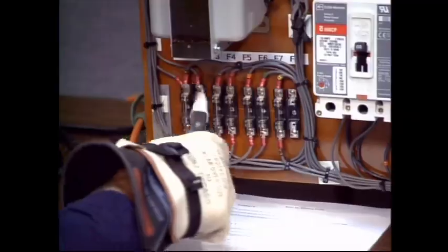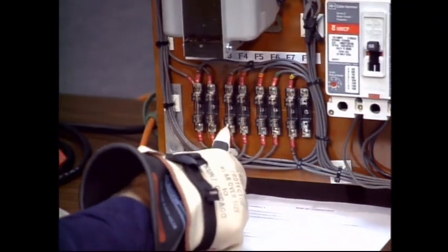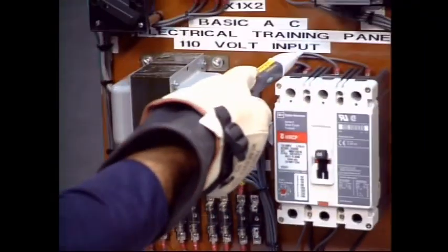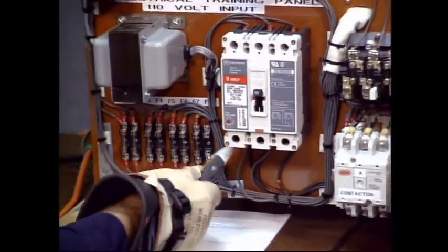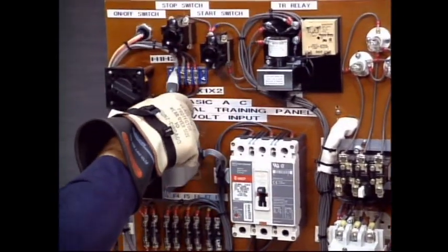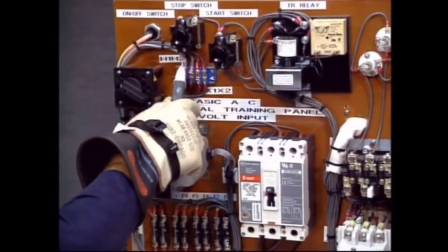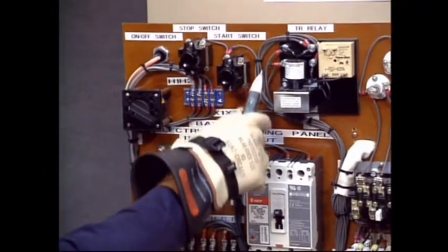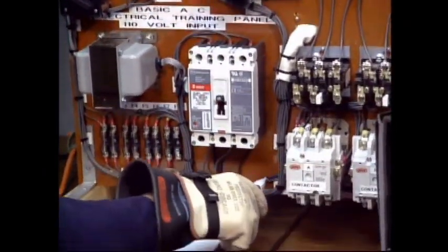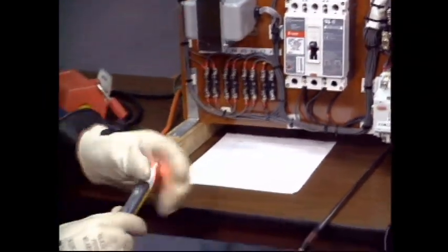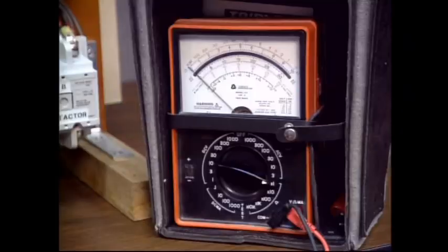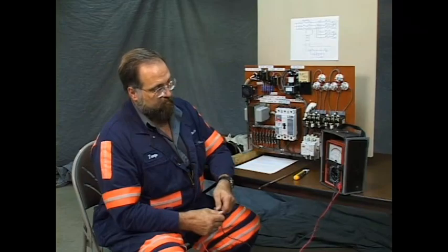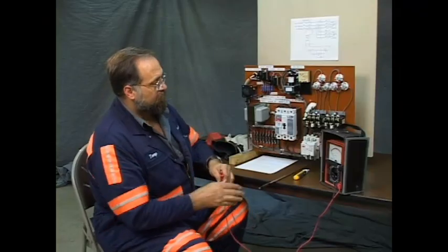Let's test the remainder of the panel with it. You'll note the little pulses of light. That's an indicator that the voltage tester is operating. When it finds power, it locks on, gives you the tone and a constant light. I'm not finding any power. I believe we're safe here. I'll turn this off. Take the gloves off. After we've taken the gloves off, let's take our test instrument. I'm going to check it for calibration. We're accurate there.